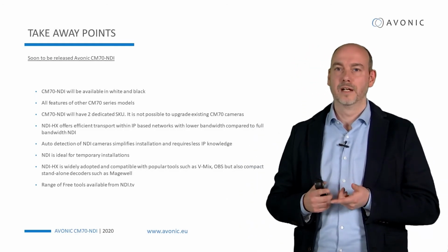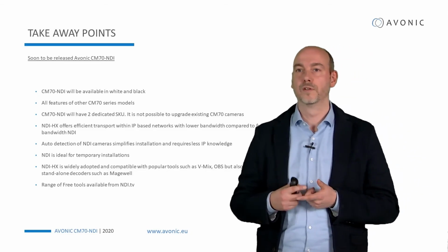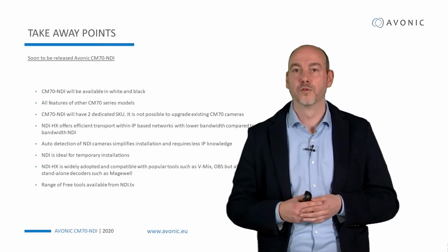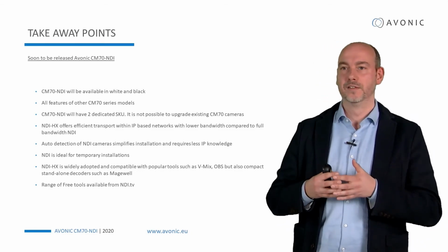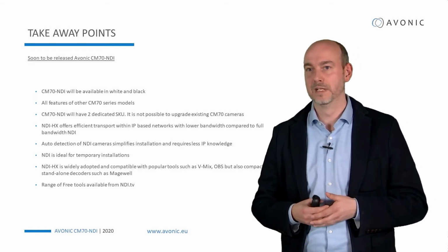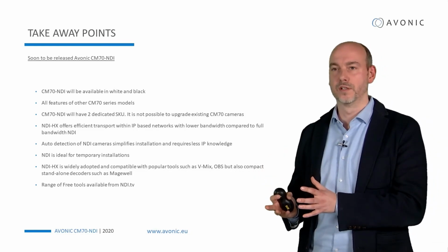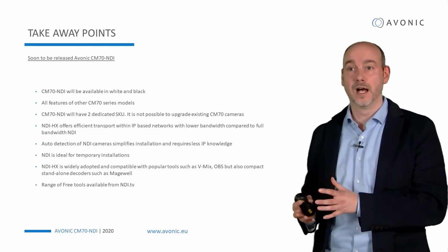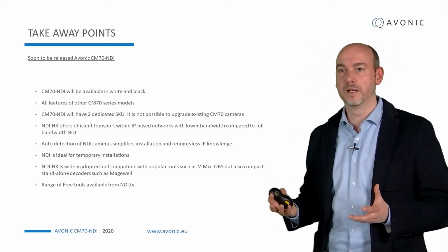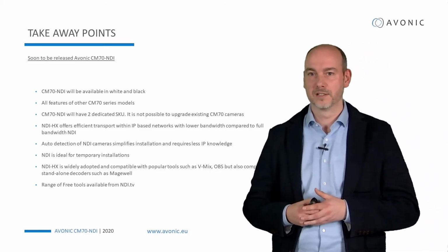NDI HX offers efficient transport within IP-based networks with lower bandwidth compared to full bandwidth NDI. So it significantly reduces the need for high bit rates. And this is important because original NDI really comes from the broadcast industry where people were looking for a replacement for SDI cabling. In Pro AV, we don't have these big infrastructures, we don't have these big network switches. It has to be affordable, so NDI HX just takes care of things.